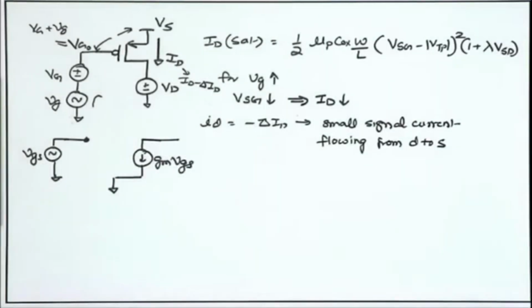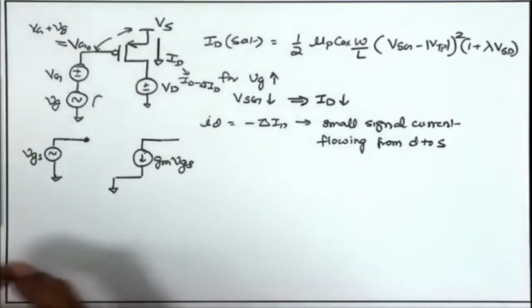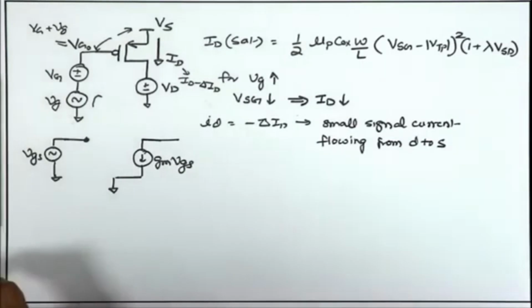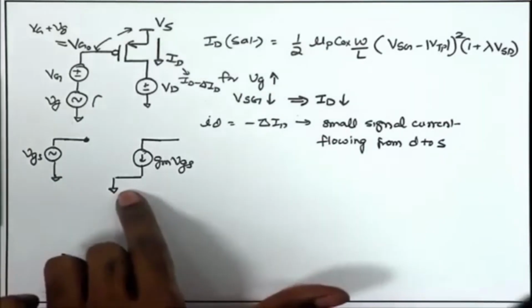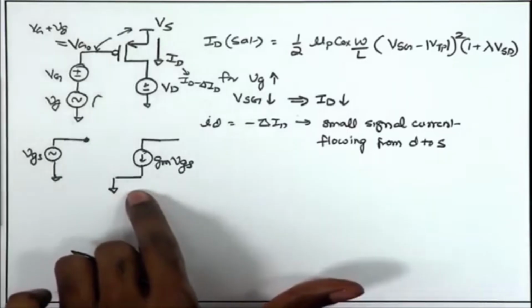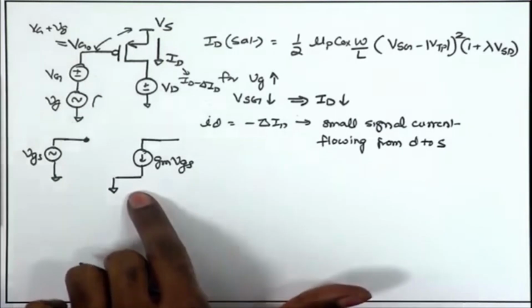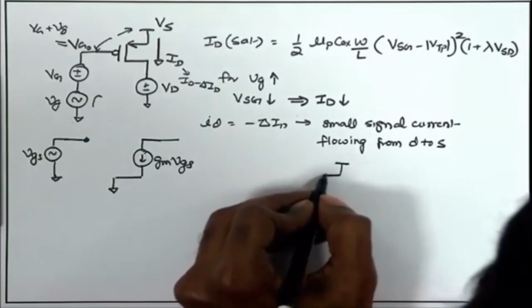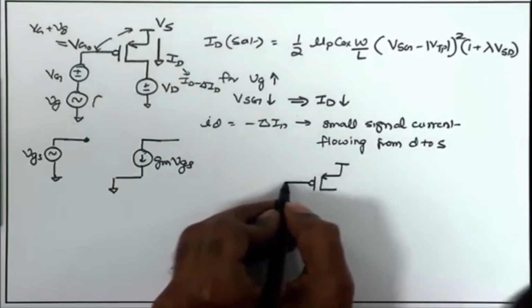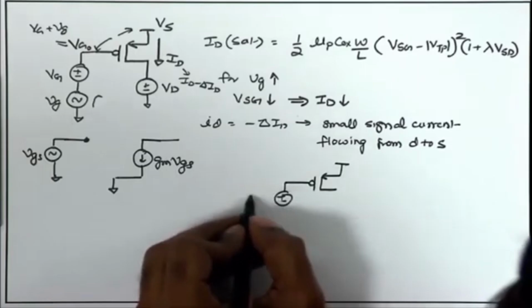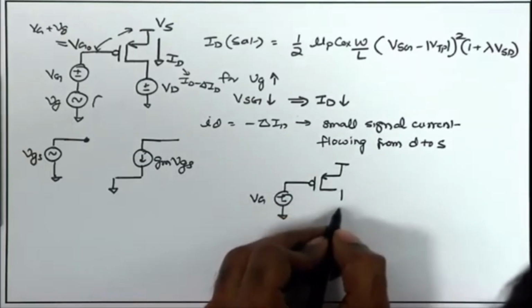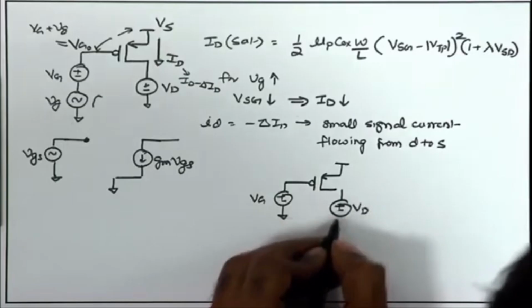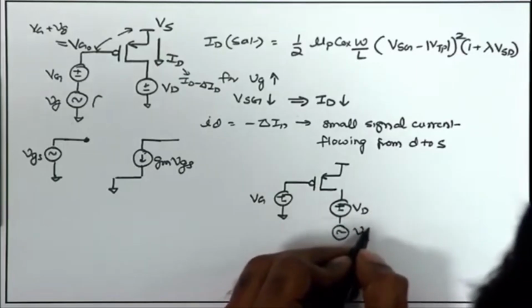And likewise, if I want to talk about Ro of the PMOS, once again, of course, it is supposed to be the small signal resistance of the PMOS. How does it change? Of course, it has to be positive because we are talking about small signal resistance. So, there we should not be so much concerned about the polarity, but just to confirm that we are getting consistent polarity according to this definition. So, in that case, if I keep my gate voltage at a fixed DC Vg, and now on the drain voltage I have an AC signal, small Vd, on top of the DC.